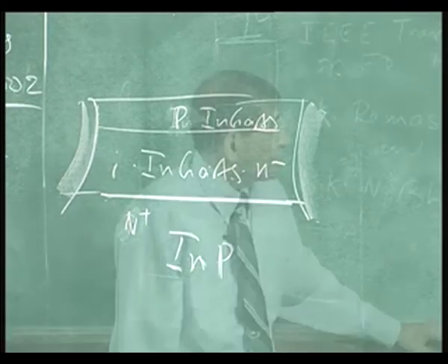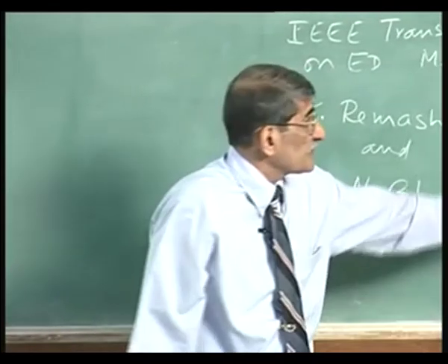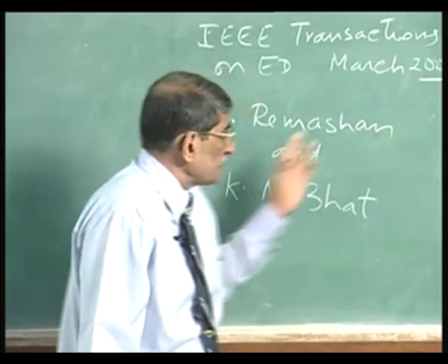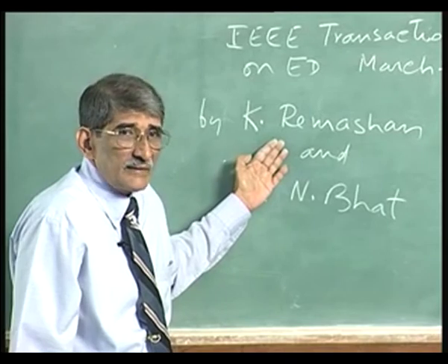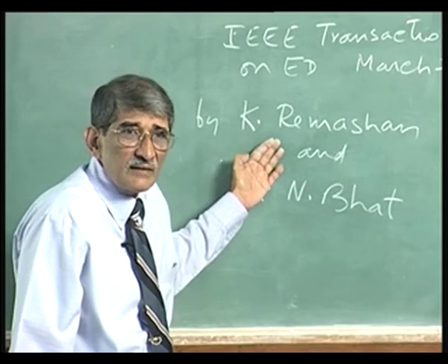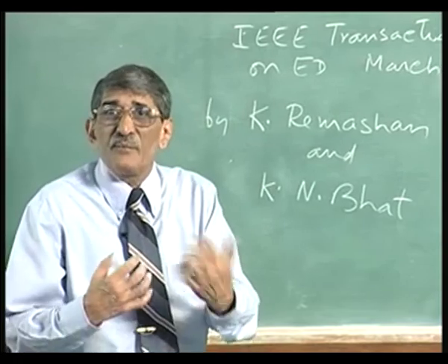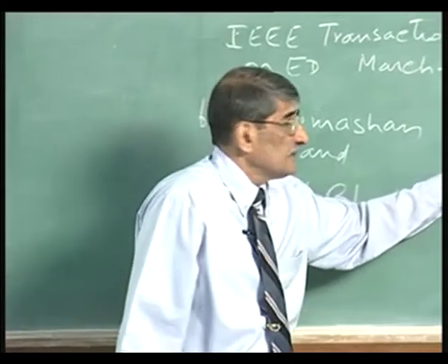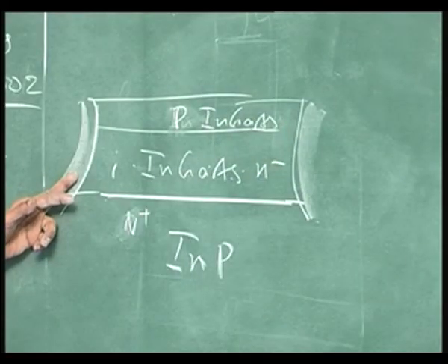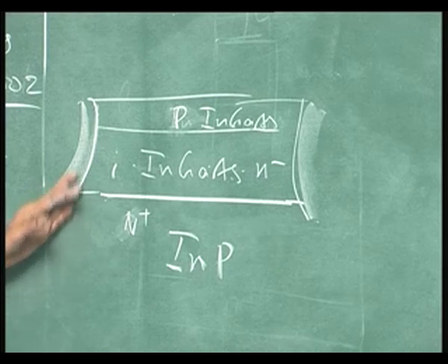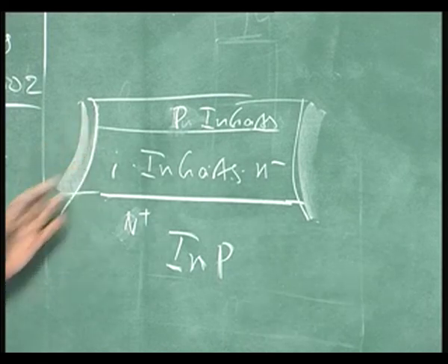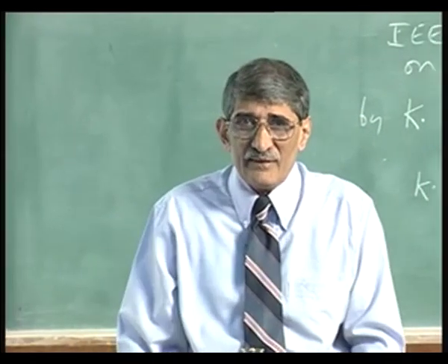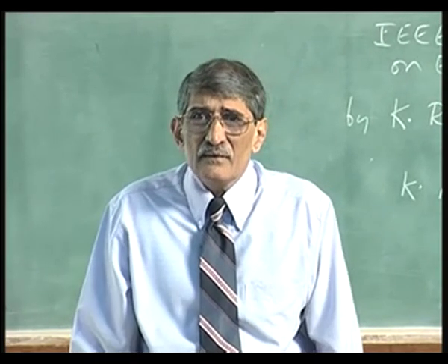So, when you use ammonium sulphide, it is not sufficient, you put a coating of another dielectric material. One of the things that is done is PECVD nitride, which worked out very well with annealing etc., because when you deposit PECVD, there are some damages which come up because of the RF. But here, what we have tried out, in fact, as part of some MS degree program, passivate with ammonium sulphide and then deposit polyimide. Here is just spin polyimide. Very easily you can put a coating of that. That gives excellent leakage current.